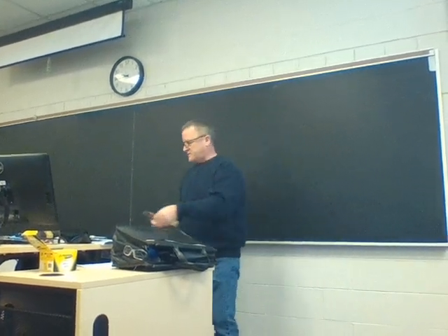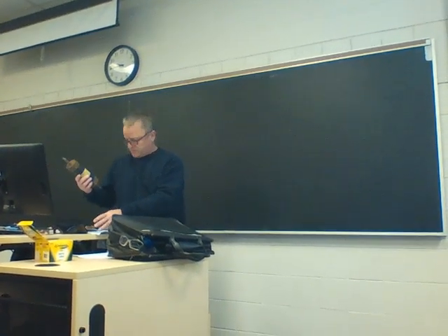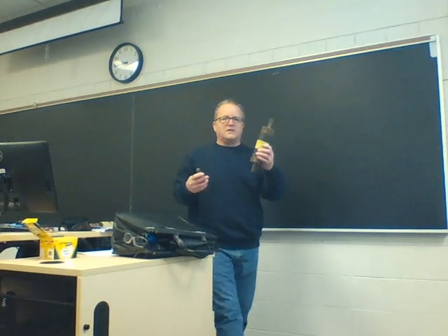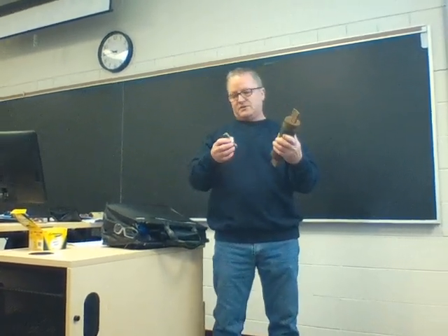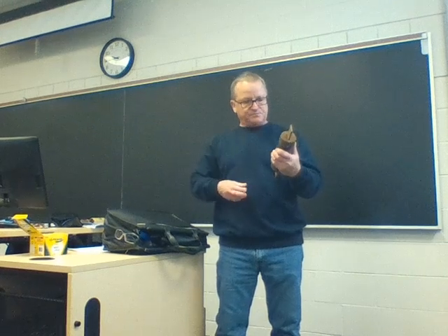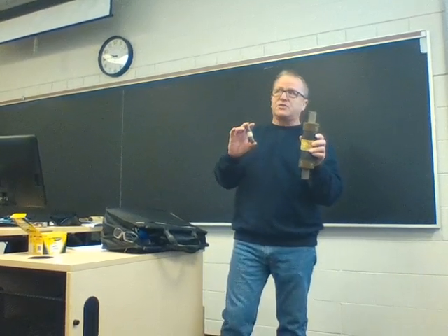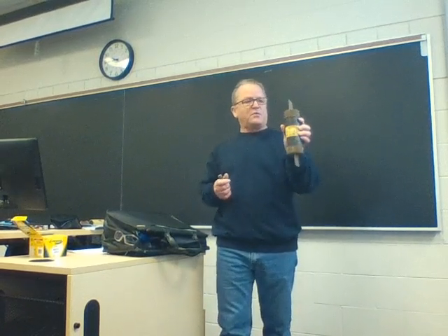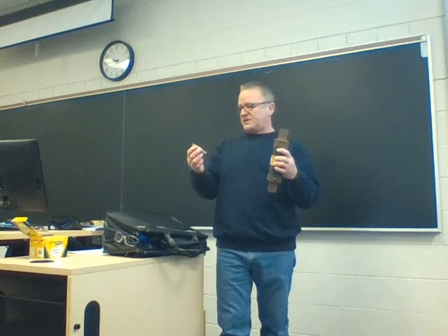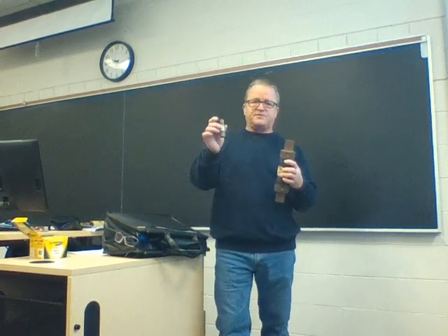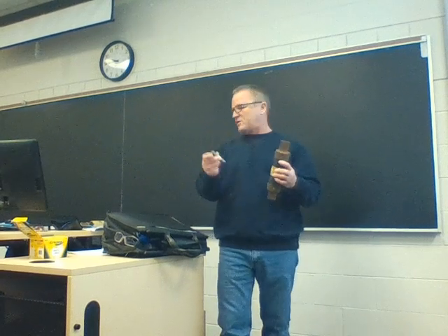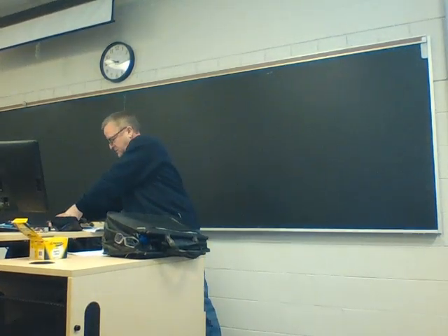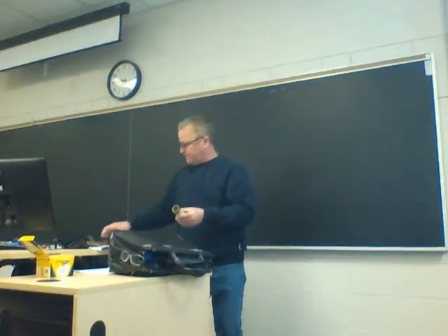There's different sizes, types, styles of fuses, depending on the voltage, the current, the class of the fuses, depending on the use. There are many different styles. This is a 600 volt, 400 amp fuse. Your standard 60 amp, 250 volt cartridge fuse, you see it in an older fuse panel in a residence. This one, fusible link is 200 amp, 250 volt.